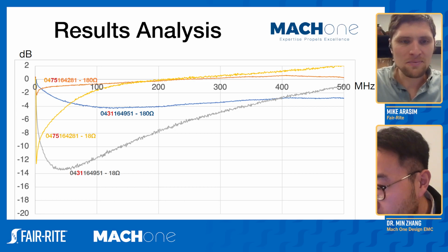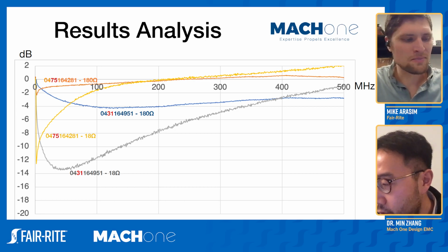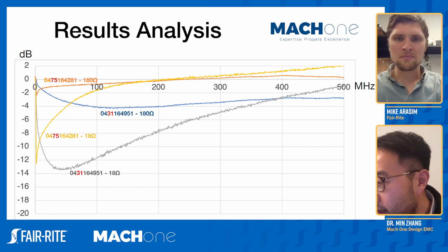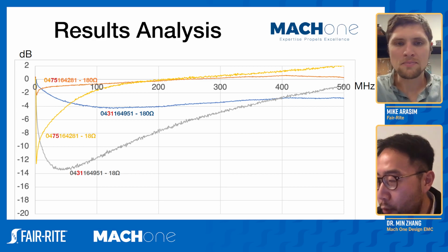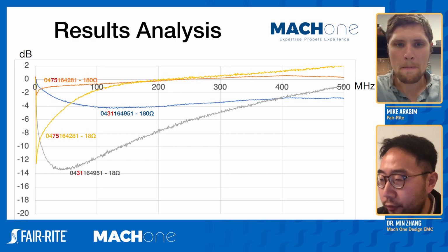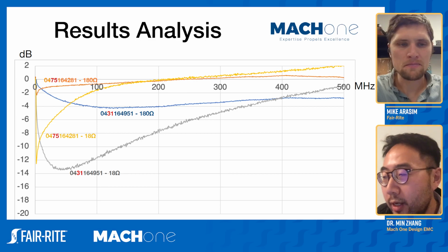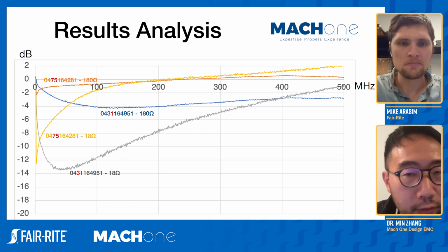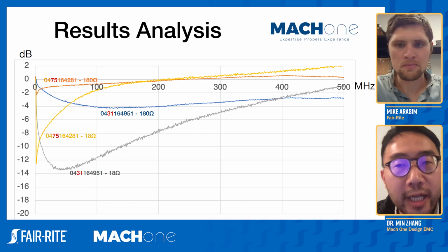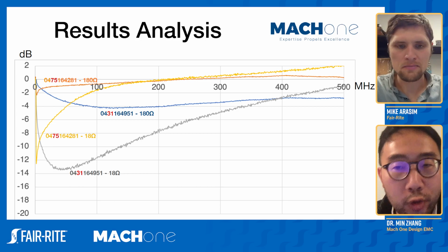It really shifts. It depends on the circuitry, and here, again, at 300, 400 megahertz, if you look at that wire made a few inches long, then the impedance of the wire perhaps already exceeds about 150 or 200 ohms.